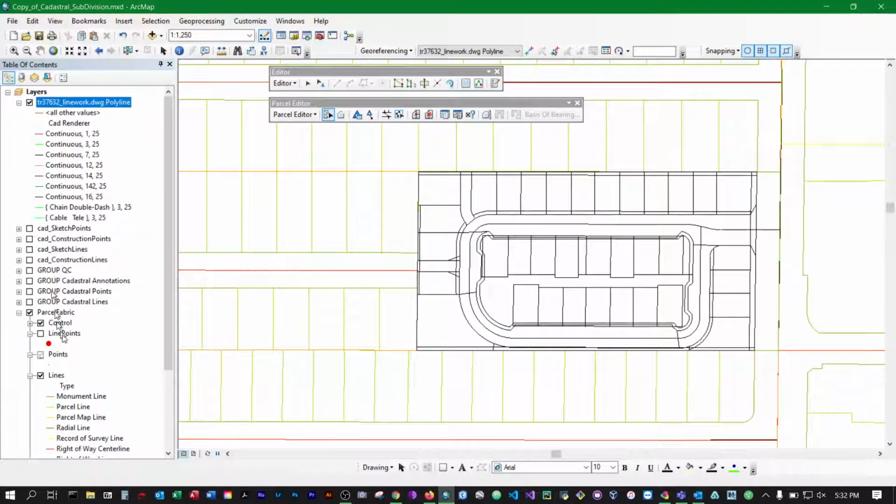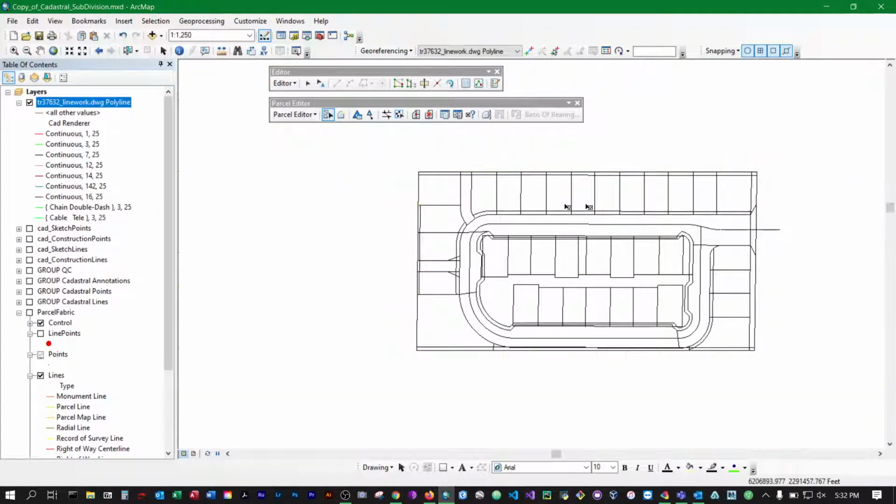So you have a few options here. Something you can do, if you choose, is go ahead and do the outer boundary first and then copy and paste that into the new plan. You could also do your road center lines, copy and paste those next into the plan, and so forth. So for this example, I'm just going to show you how to do this workflow, and then you can go about your process in a way that works best for you with the data.